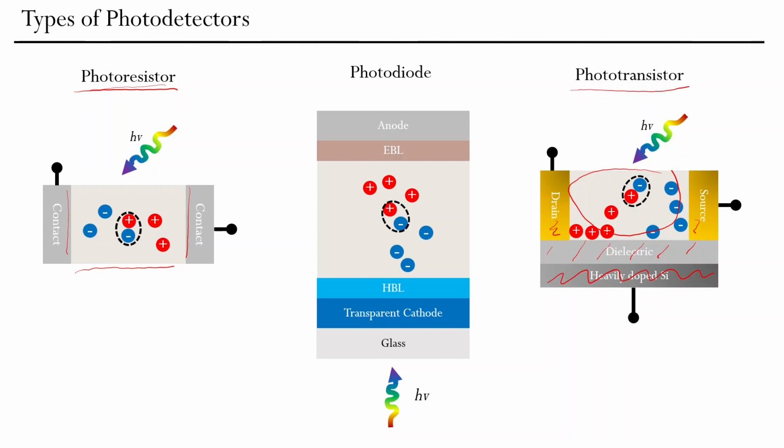We can modulate the conductivity, like the background conductivity in the dark, of this semiconductor layer by the gate potential. So we can push the Fermi energy up and down in this system because of the external electric field, which can be quite strong since the dielectric is thin.